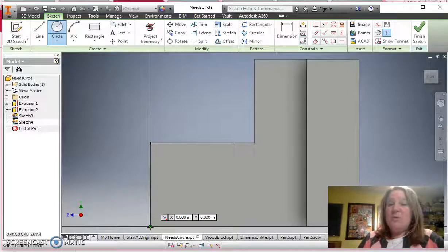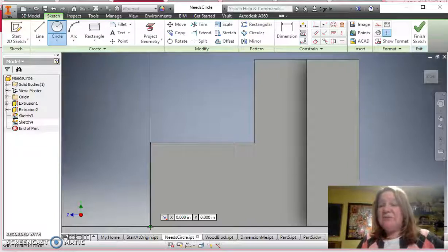So what I want to do is move that cursor over 1.5 inches to the right, so that's 1.5 inches in the X direction, and then 1.25 inches up. So I'm going to hit the tab, and you can see it moved me into there. So I'm going to type in 1.5 inches in the X direction, and then I'm going to tab over, and then I want to move 1.25 up.